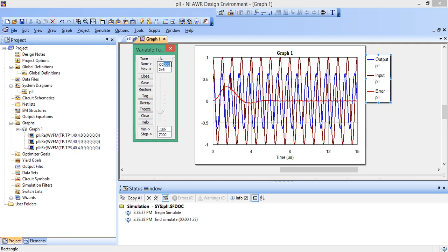Okay, so now let's increase the cutoff frequency so that we're letting higher and higher frequencies in. See what happens there. So look at this curve. I'm going to increase the cutoff frequency and then we'll see how everything changes. So I'll change it to 0.7 e to the 6, 0.7 megahertz.